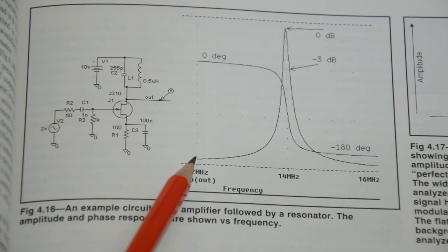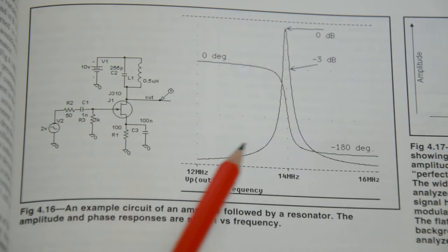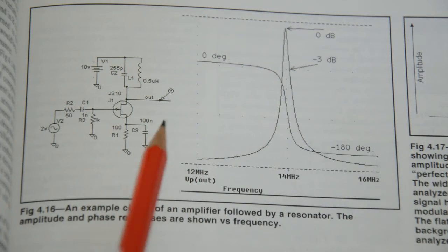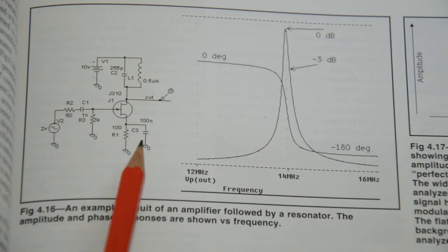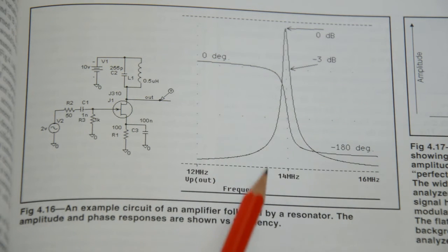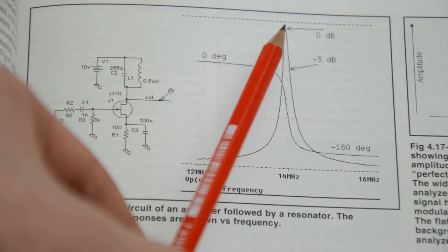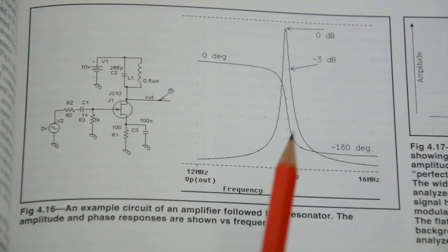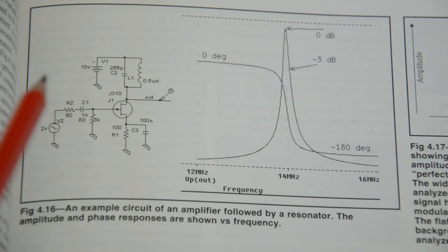So in the linear domain, that would be pretty flat here, because we'd have to compress that down in order to be able to go up to 0 dB here. So we would end up with a curve that is pretty flat and then rises rapidly towards the center frequency and then falls as rapidly as it was rising and then be flat again. So that wouldn't be too much of an interesting plot here. And that's just another way of looking at the problem and another justification for expressing stuff in the logarithmic domain.